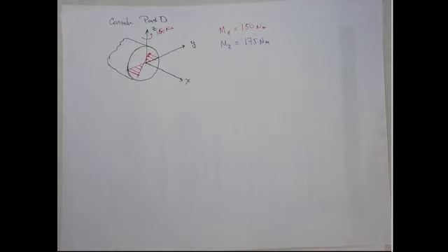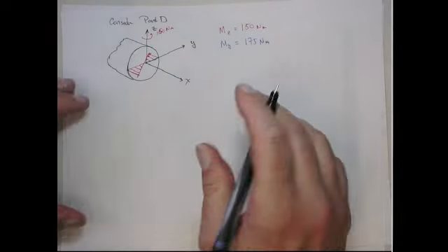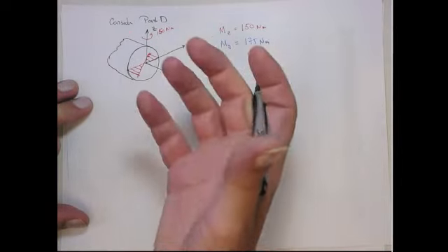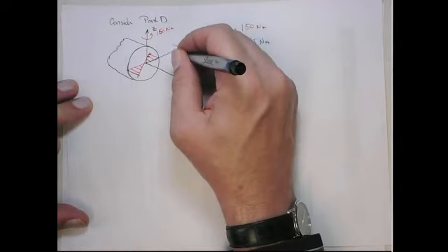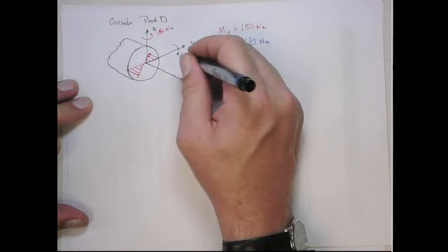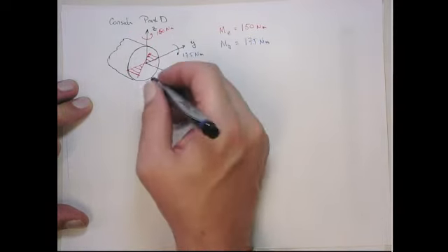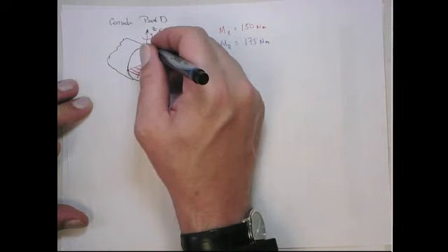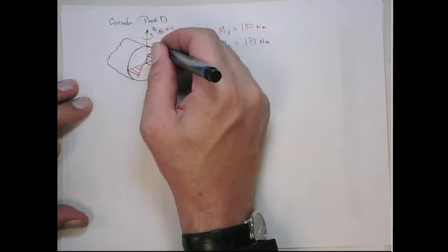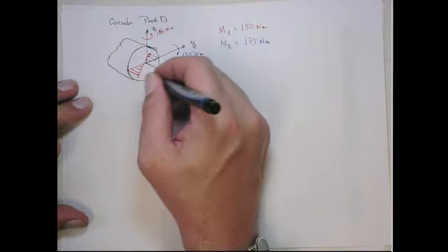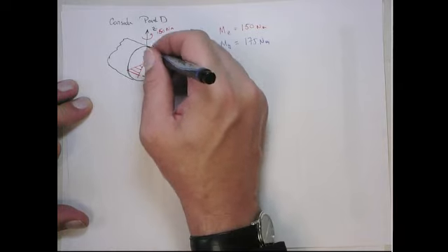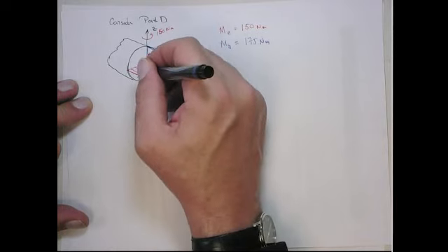But also we're going to have a contribution from bending around the y-axis. If we look at the y-axis, it's also positive. So that's going to be going this way of 175 Newton meters. And so this side's going to be in compression and this side's going to be in tension. So this one's going to come out in tension. This one's going to go in compression. So we can draw that.